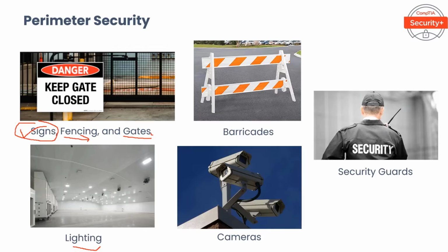Proper placement and positioning of fixtures can dramatically reduce the glare. In areas where crime is a concern, install lamps with a higher color rendering index. Bright lighting and cameras reduce the likelihood that an area will experience unauthorized access attempts. A good design provides uniform lighting, minimizes glare, is compatible with CCTV, and complies with local light pollution and light trespassing ordinances. Regular maintenance ensures that the safety and security of both people and property are not compromised. It should be at least twice annually. You need to conduct an audit of all exterior lighting.